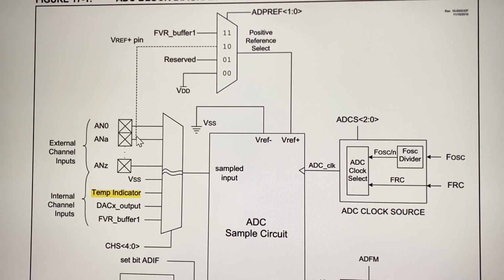And also, one of these inputs in the channel inputs is known as the positive reference voltage, and this can be selected with this code using these 2 bits. Those bits allow you to make this one a reference voltage. That way you can change the range of the sensor.